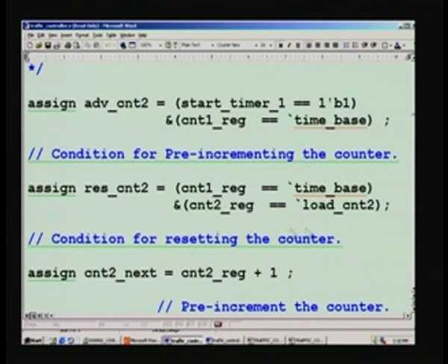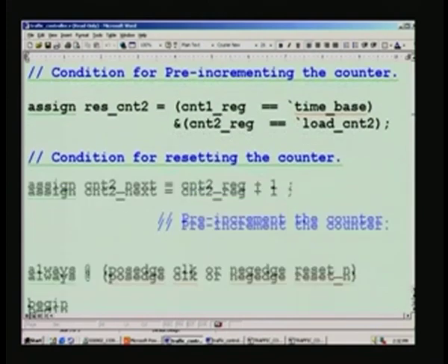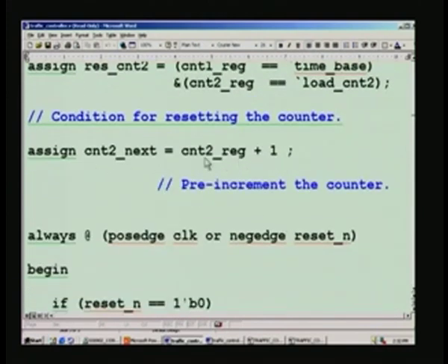That also will have a load, which we have already seen using a define statement, and when it is equal to that load value, and this is also advancing from 0, 1, 2, 3 and so on. Finally, it will touch the load count, which is the fag end. For example, for 45 seconds we put it as 449 there. When it touches 449 and this is equal to 4 million minus 1, then only this counter will be reset, and once again you have an advance increment for the counter.